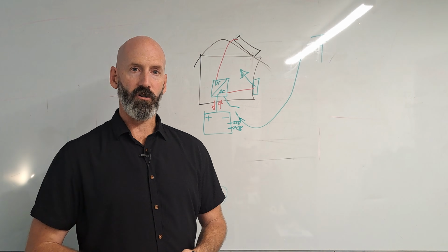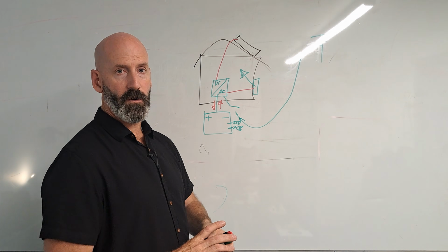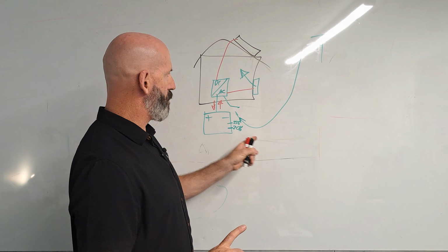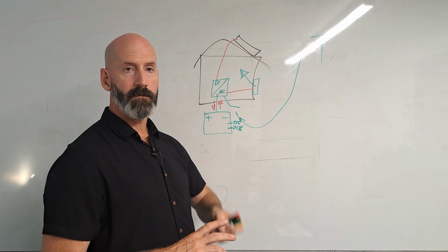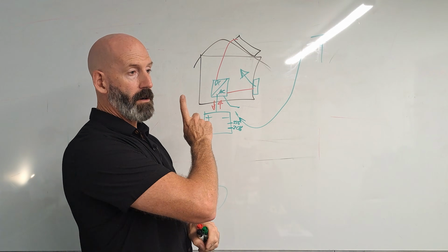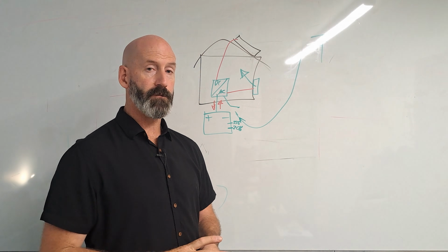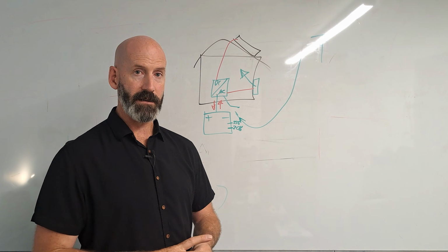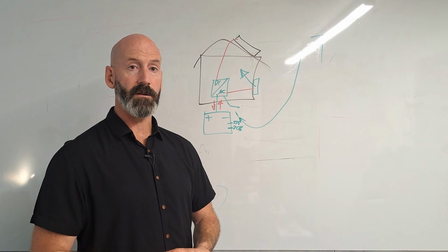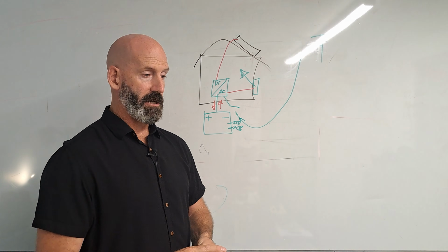And what they tested and tried was to send a high frequency signal down the power lines, trigger the inverters, not an off-grid system, in a hybrid, and force it to discharge the home battery back onto the grid without any control from the homeowner. They just send a high frequency. This is why you'll find all your hybrid inverters are grid interactive. If they are approved for use in Australia, they must be grid interactive. Off-grid doesn't have to be because they are designed to be standalone. They're not designed to be controlled by the grid. So that is a really big consideration going forward.